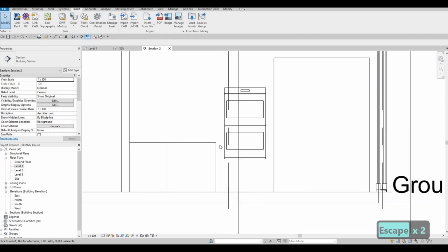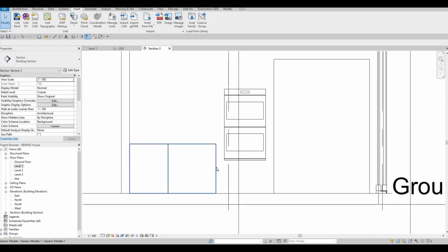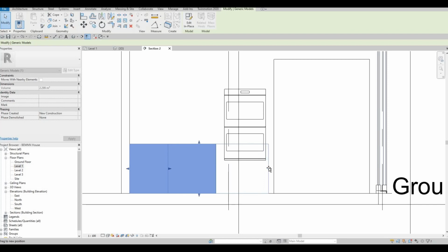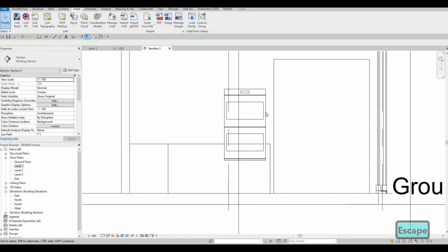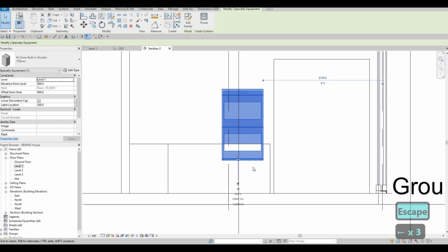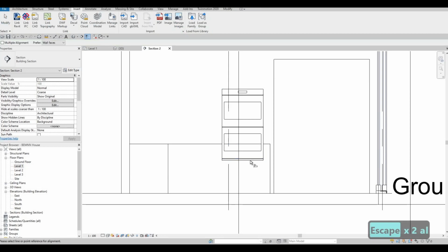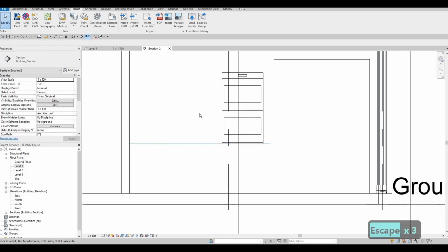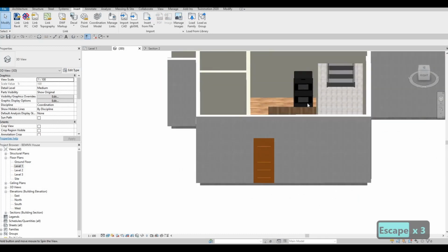here. So what I was thinking is we could do the things that we did earlier, move this one a little bit right there, and then let's just push this up. So we have the same cabinetries right here, and then we have a different cabinet that is enclosing this spot. So we could actually do that instead. So I'm just gonna use align AL to align the bottom, and then if we see it, it will look like that.